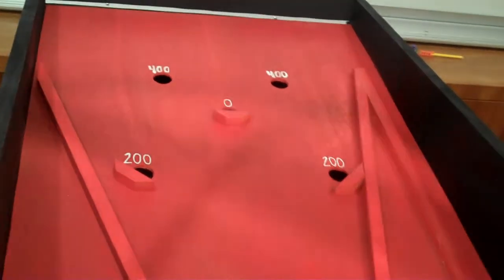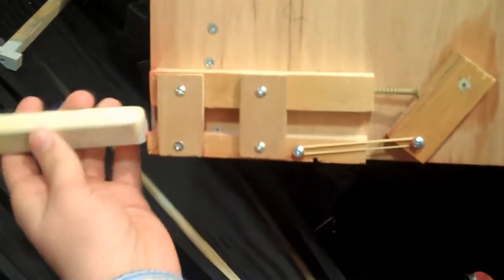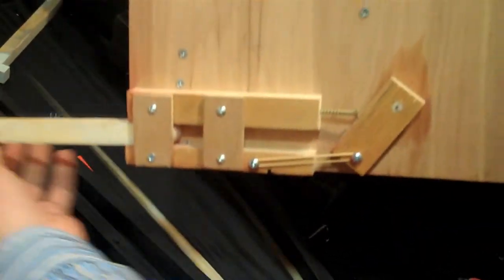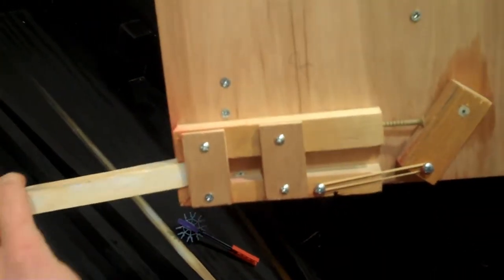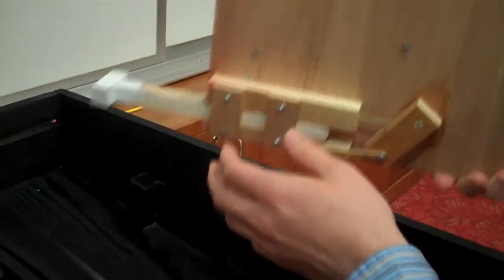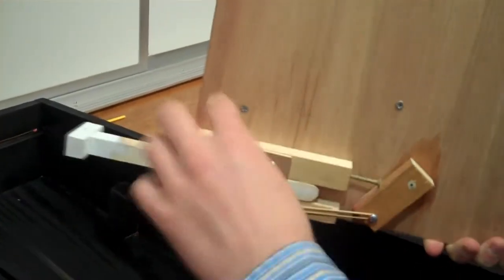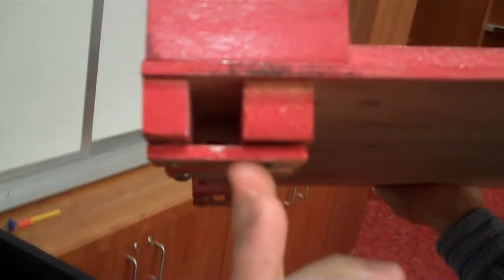I'll show you the flippers underneath. As you can see, we went with the elastic approach with the actual game board flippers rather than having those twisting versions. For this, we have the plunger pieces going through, and right here acts as a guide in order for this not to move around. These pins right here, since this is all upside down, if these weren't there, the plunger itself would fall through. Originally, it was a little bit too close, and it made a lot of resistance, so we had to put some washers right there.